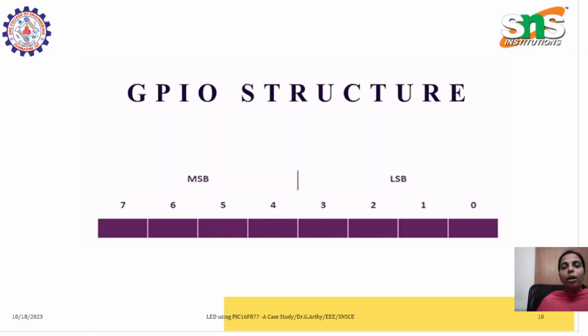Any other output devices as well as input devices can be connected. So if I want to connect these IO devices, then how do I access these ports? We have 33 port pins, general purpose IO port pins, and how I can connect these IO devices to those ports, that is what we are going to look into here.